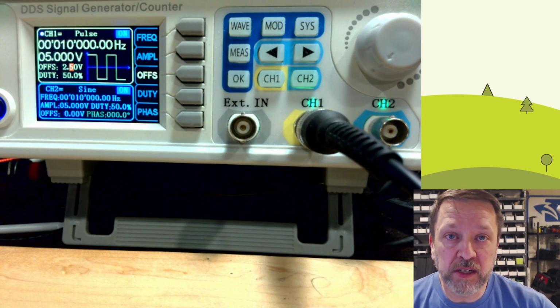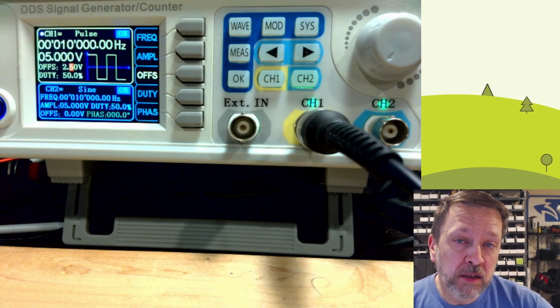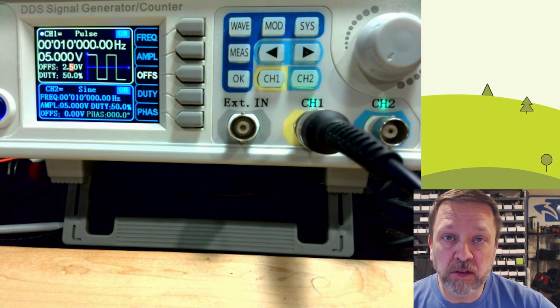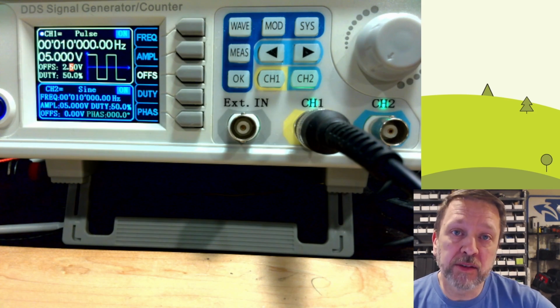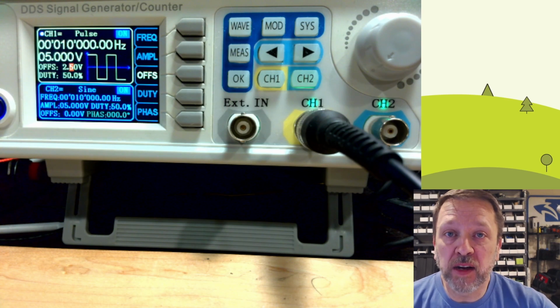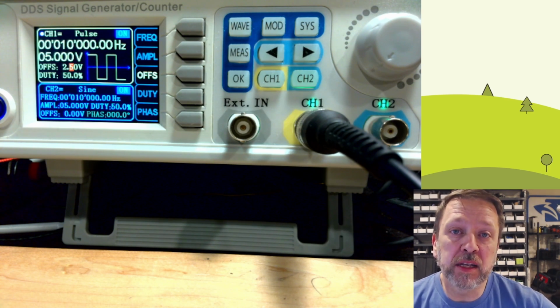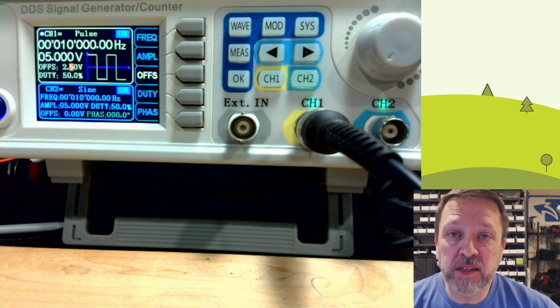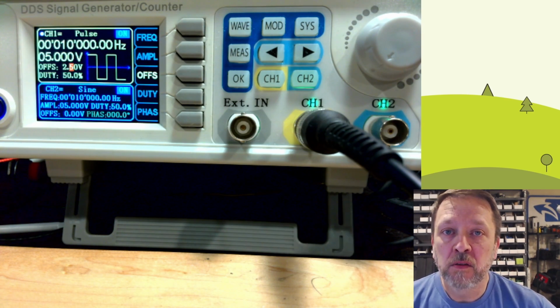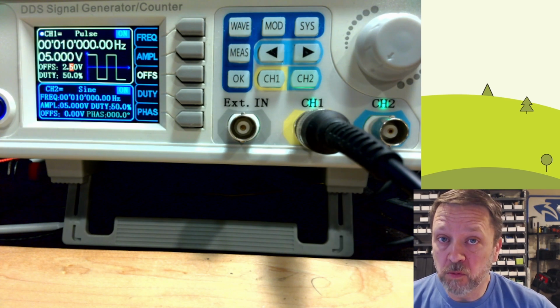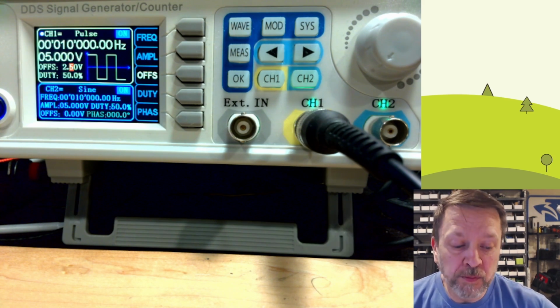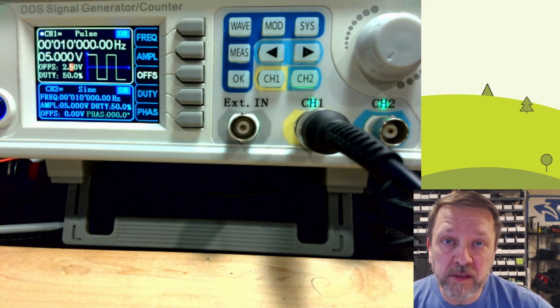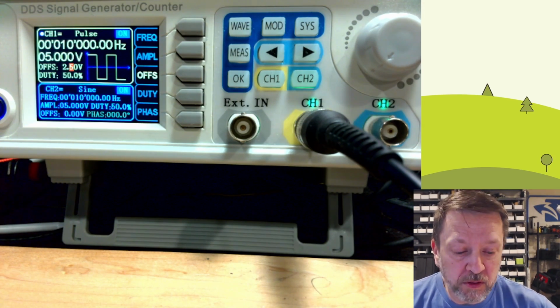input on your device. Many devices today use 0 to 3.3 for their voltage on the bus and for their logic, but they're called 5-volt tolerant, meaning that you can give it 5 volts and it won't harm it, but it really doesn't need anything more than 3.3. The reality is logical on is usually well below 3.3 and logical off is above 0. But we're going to try to go with 0 to say 3.3.